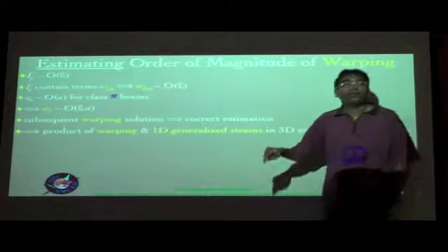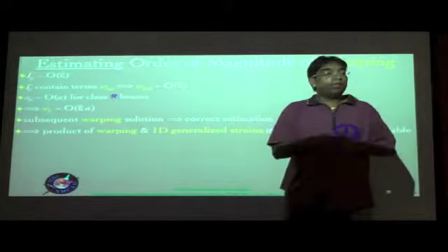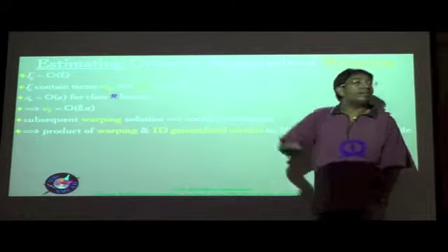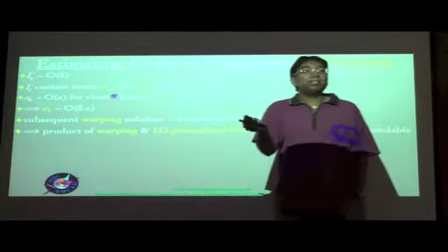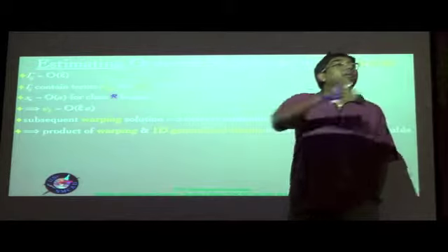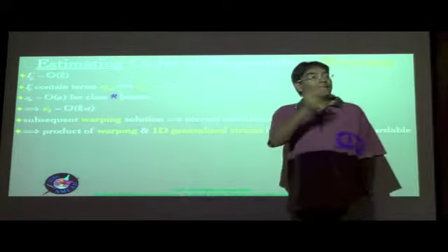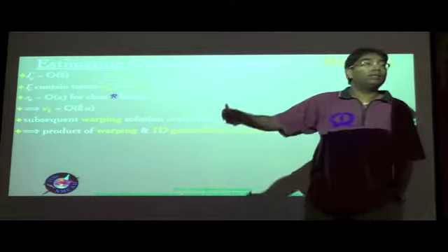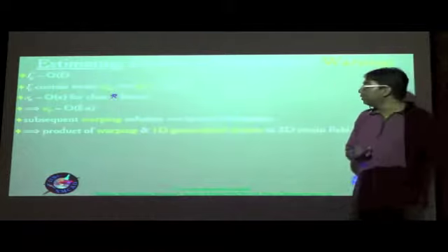But in situations where the 3D stiffness matrix has all terms of the same order of magnitude, then irrespective of whether you do the dropping off of terms at the strain energy or at the strain, it is one and the same. They are equivalent to each other, because the strain energy is defined as a quadratic in the strains multiplied with the 3D stiffness matrix.